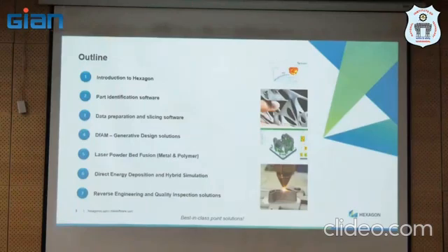What it will do is search for a similar material available with 3D printing, because 3D printing has limited materials as of now. You take polymer or metal. Let's take the example of metal which we have done for one of the university race cars recently. It was printed with aluminum, but in aluminum there are only two grades available for 3D printing. That is AlSi10Mg and the second is a lower aluminum with some alloy material.